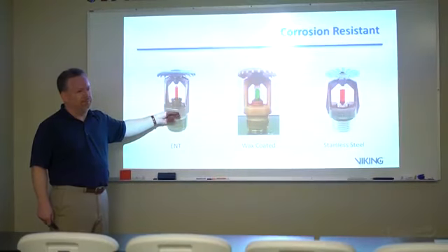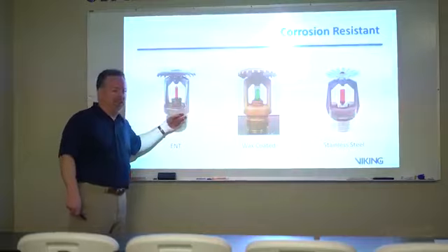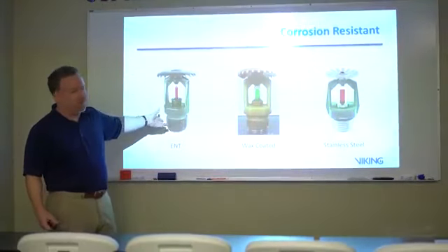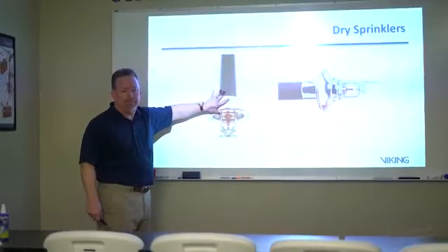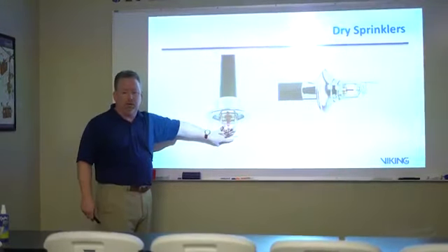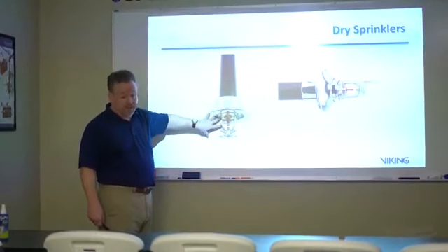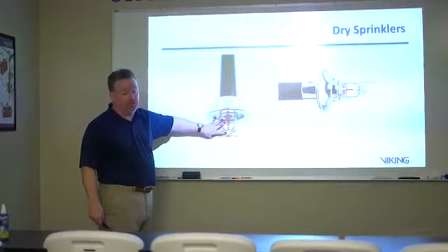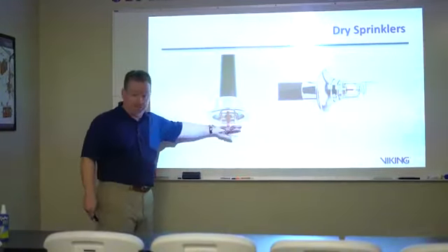ENT's only been around, what? 4 to 5 years. And so basically we've said, yeah, we got a drop-in replacement for you, but you got to go ENT to do it. And this is one where you probably will find it used extensively: when you're dropping in from a wet pipe system into an unheated or cooled area, freezers, cool warehouses, things like that, where the temperature is going to get down below 40 degrees in the space that you're protecting. So food warehouses, things like that.